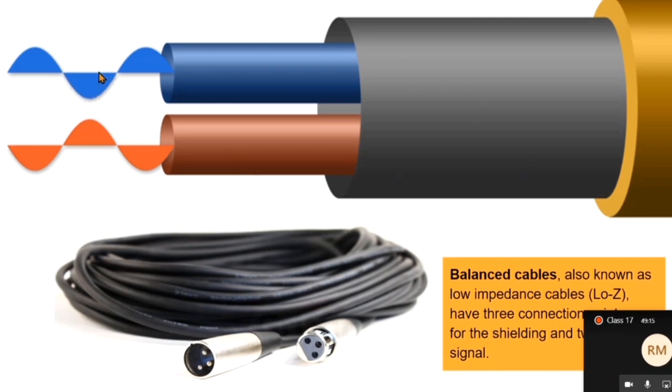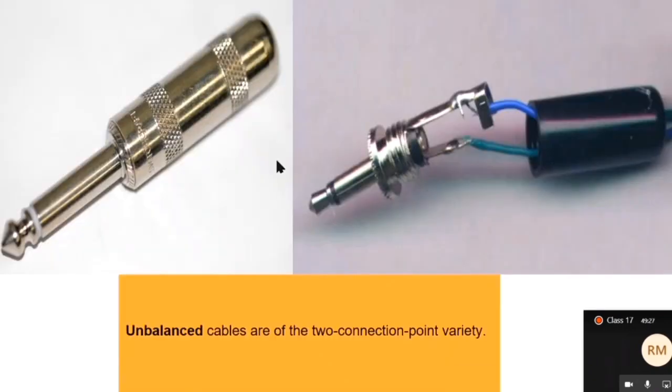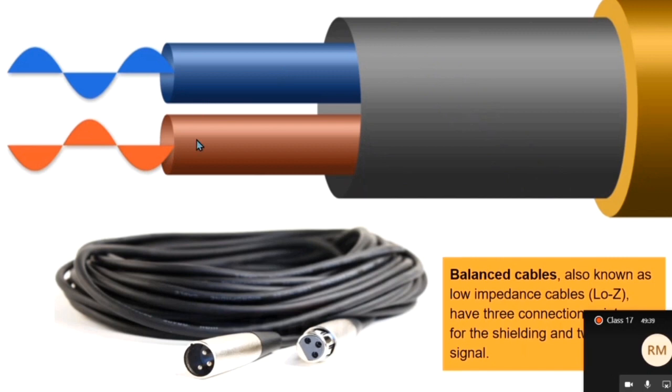Now, what is amazing about this is you can send the signal much, much further than you can with unbalanced cables. You get a guitar cable that's longer than 25 feet, it's essentially an antenna. But you can send balanced cable signal something like 350 feet before it becomes a problem. The magic maneuver is that any noise accumulated in its journeys along that 350 feet will be canceled via the property of phase once the signals are resummed at the other end.